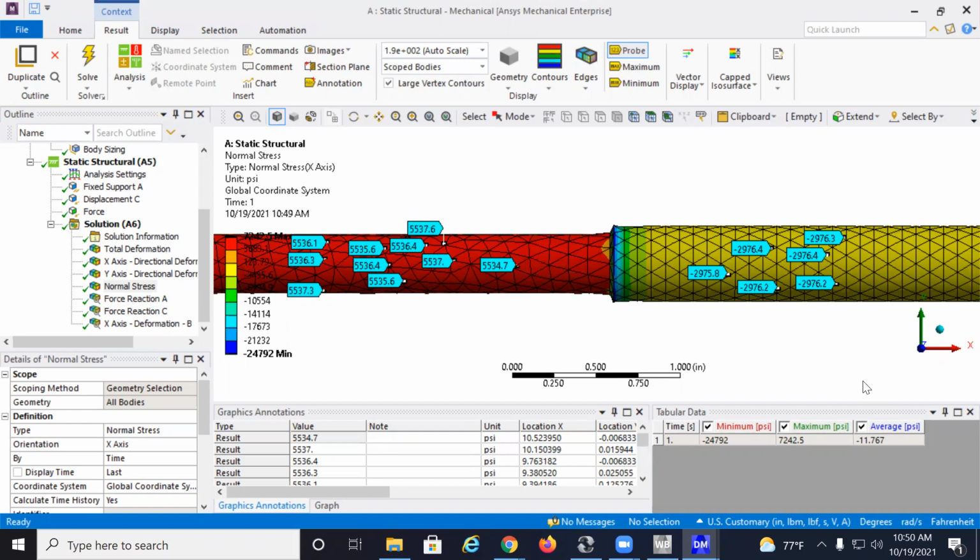But again, I emphasize, I do not have an option to look at a normal force because I'm not using beams. I'm using solid pieces. So all what we can do is to look at stresses, we can look at strains, we can look at displacements. We can even look at the state of stress, like use that to calculate at any point. I can calculate a von Mises stress, calculate the principal stresses, look at the shear stresses at any given point.